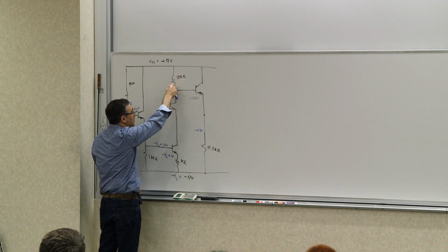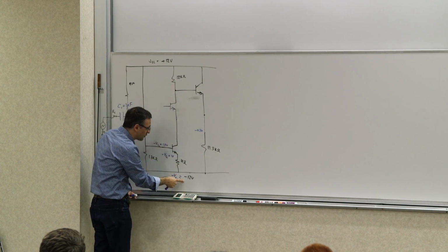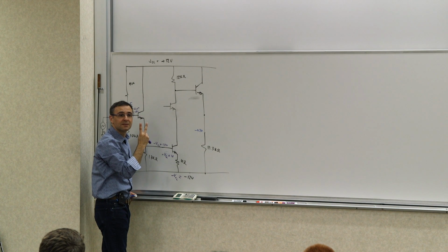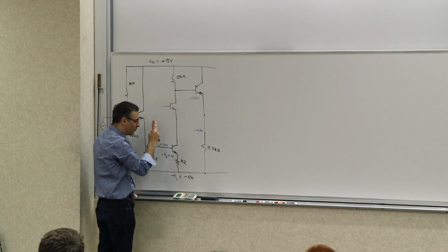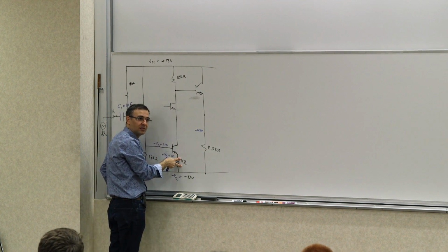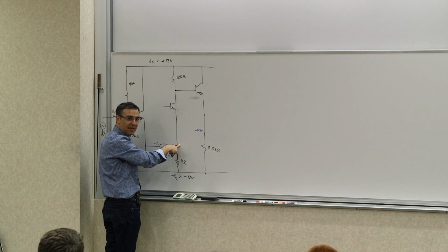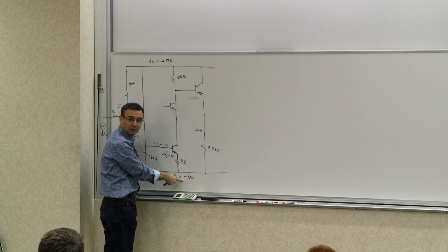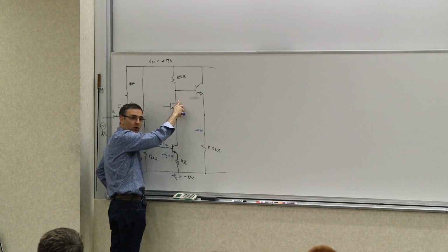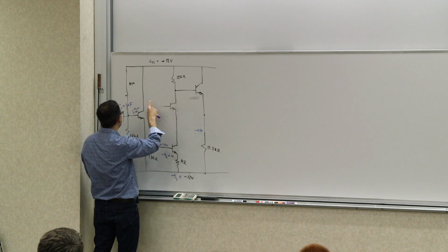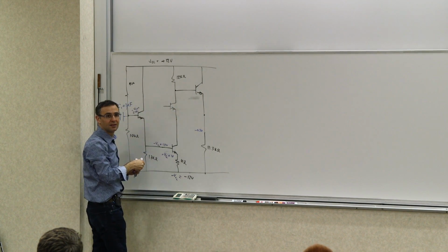Let's say this is to be pulled down all the way to negative 12 volts, the current has to be 2 milliamps. If you're drawing 2 milliamps, there's 2 volts here, plus 0.2, so this means that this can be at lowest 2.2 volts above the minimum voltage. And I need another 0.2 for this before it goes to saturation, so 2.4. So it's kind of a similar breakdown.